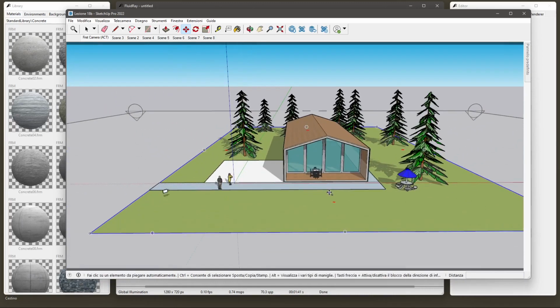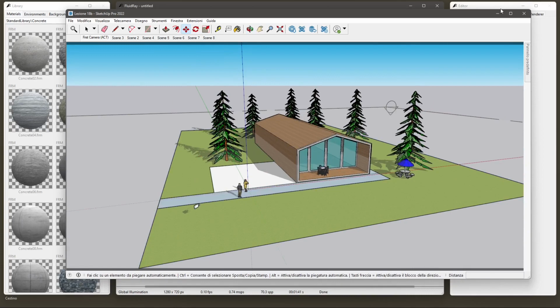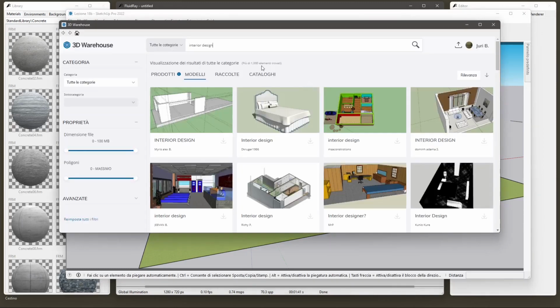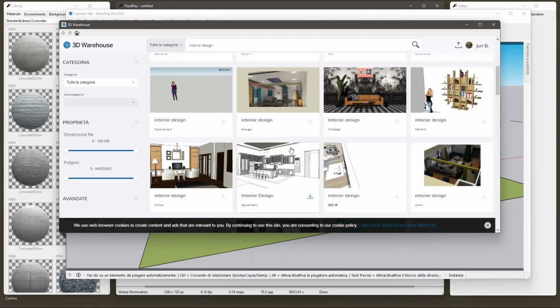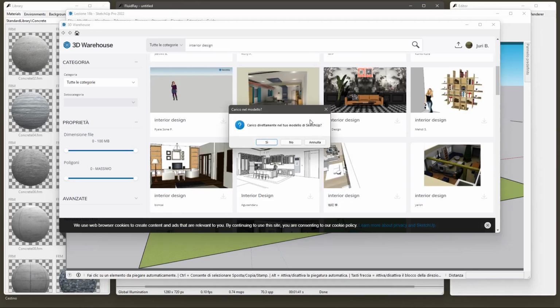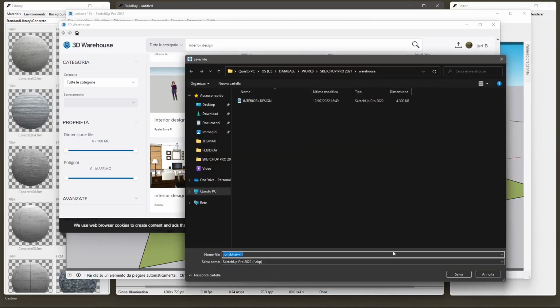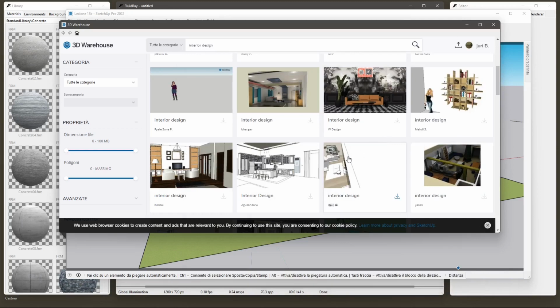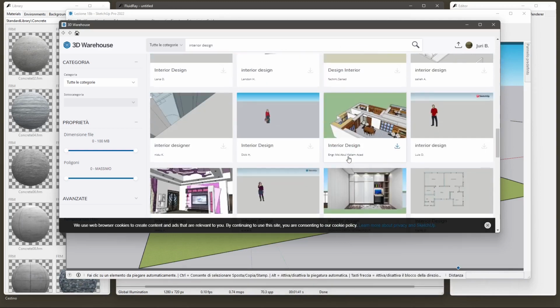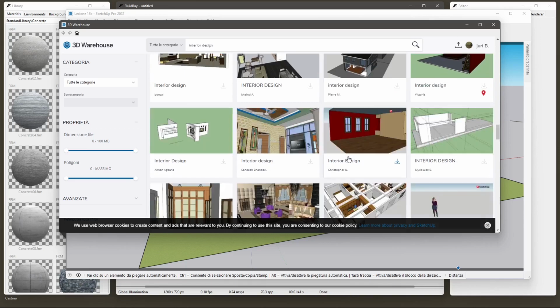So the one important thing is that you cannot do any, let's say, scene creation or any modeling in FLUIDRAY. So what needs to be done for the scene has to be done inside the software that you are using. So if you're using SketchUp, make sure that the scene is ready and just save it and then import it. So you need to assemble your scene with all your exterior, interior design, furniture, and furnishing, appliances, whatever.